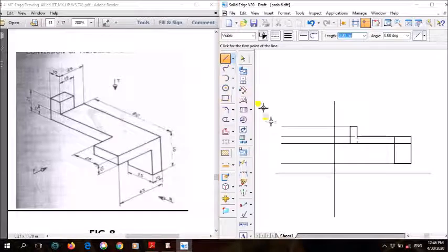So the same way, again using a thick line, you can start from here. The height is how much? 40 mm. So draw from the bottom extension line, from there draw a line in the upward direction with a height of 40 mm, right? That is from here to here. Now we'll draw this surface, how much is it? 45. To the left side, draw how much? 45 mm.